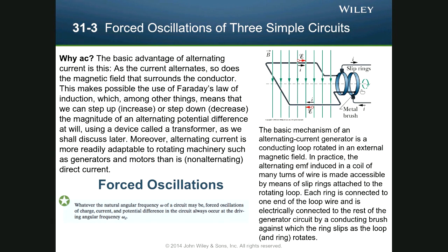But the ability to step up and step down voltages meant that you could step up to a large voltage and make a tiny current, and that your tiny current would only be the source of thermal losses in your wire. This allows you to transfer power over tens of miles instead of tens of meters, instead of hundreds to thousands of meters.